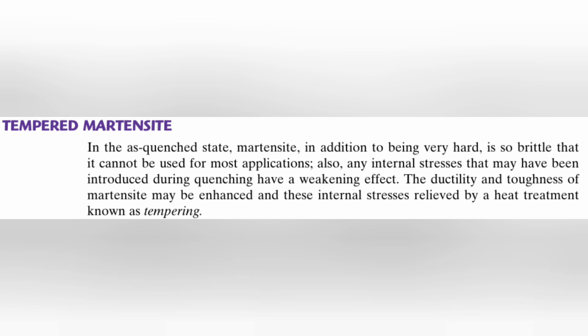So in addition to that, also any internal stress that may have been introduced during the quenching has a weakening effect. The one thing you have to keep in mind is that the quenched steel would have a weak strength. We are rapidly cooling down to a very low temperature. It will be brittle and it will be having very weak strength. Of course, it will be hard. Obviously, it will be hard, but it will be weak.